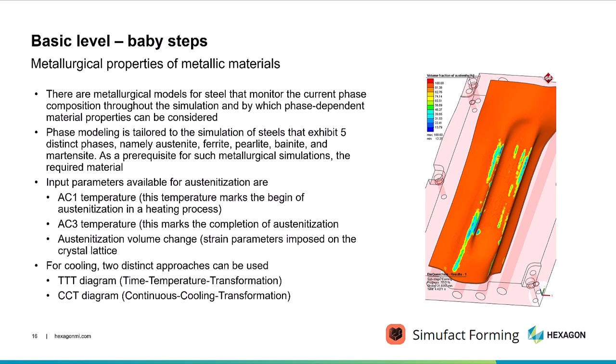And you want to monitor, for example, how much martensite you are forming or what's the cooling rate that you are expecting for certain locations of the die. And simulation can certainly help you with that. Simulation would need a lot of input data, for example, how the material transformation happens, and you can get that kind of information from the dilatometry test that you run on your Gleeble machine.